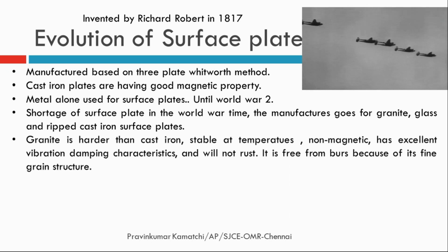Granite is harder than cast iron, and it is more stable at high temperatures also, and it is a non-magnetic one. It has excellent vibration damping characteristics, and it is not going to rust. Granite is free from burrs because of its fine grain microstructure.